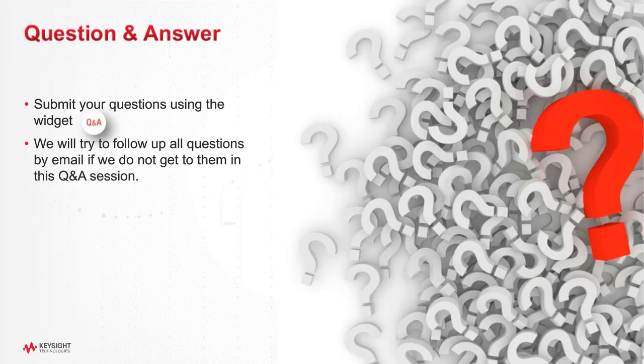Great, thanks. And here's a question from George. For voids and slots, did you parameterize the design and simulate them once? And what tool did you use for it? The answer, yes, I did parameterize the design. Otherwise, it's too much work. And then simulate it once by running more like a sweep simulation in the tool. For this example, I used a tool called EM Pro, which is a full wave 3D EM solver. That was the one I used in this application.